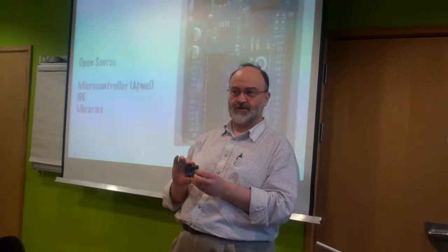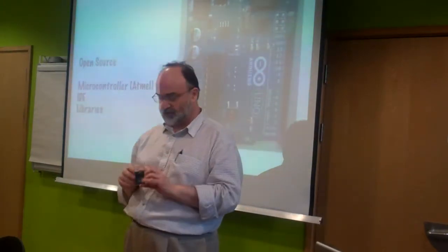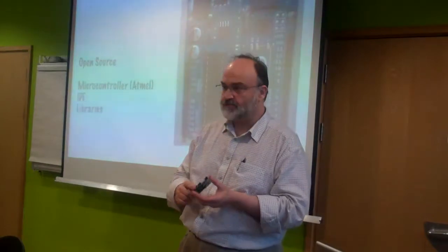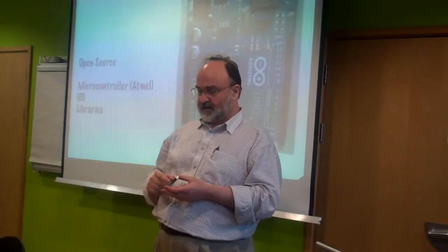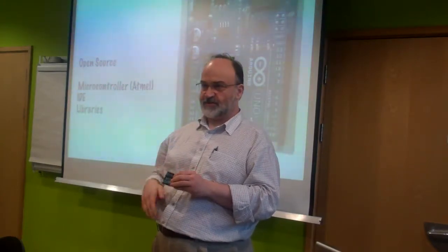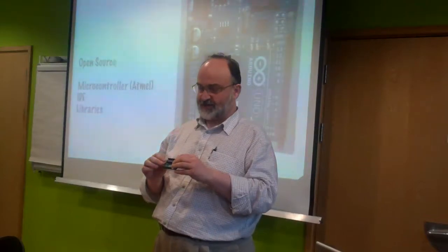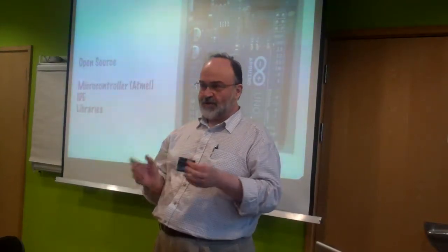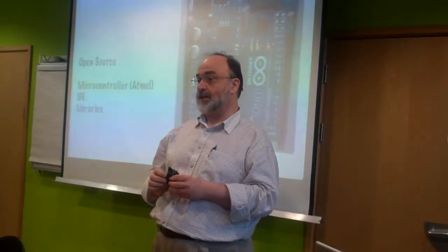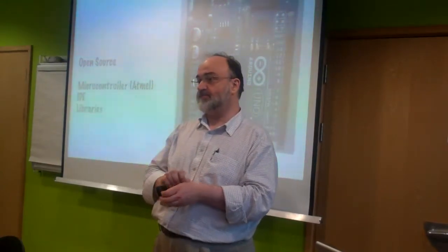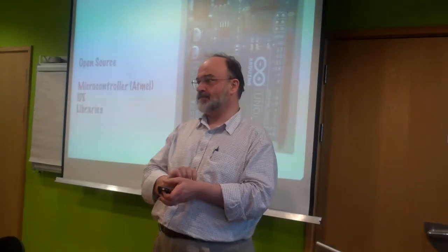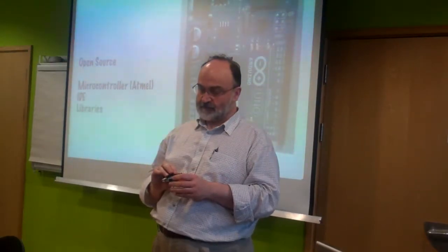So this is a big one, plus people started out on much smaller systems. But the important point is, it's real time, there's no operating system, there is zero between the library and the hardware. It runs at about 16 megahertz, which is far faster than even you guys can think. And so little things it can do very, very quickly. And it is just about possible to create a television picture by wiggling its pins. That's about how fast it is.